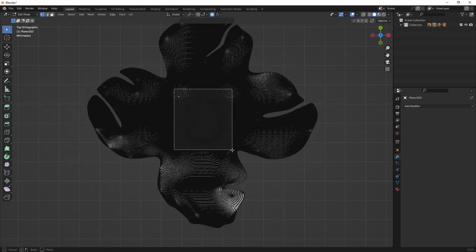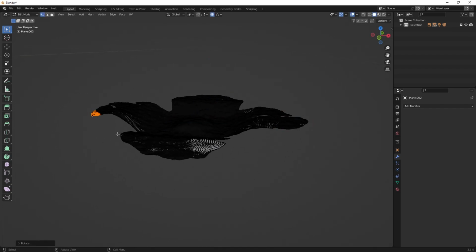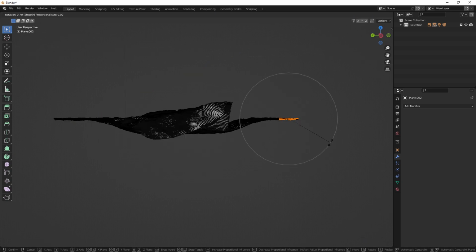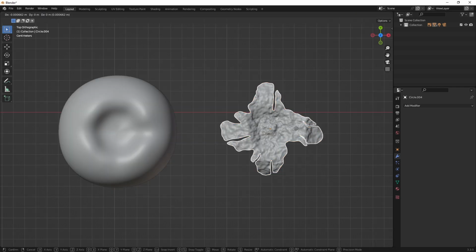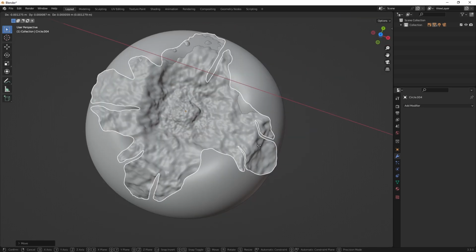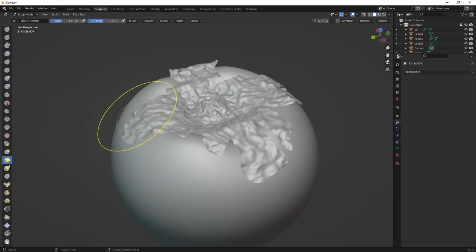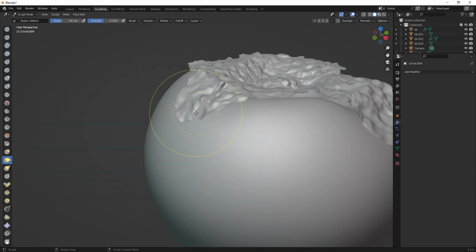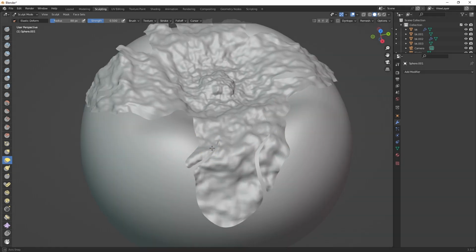The Persimmon's calyx is tightly fitted over the Persimmon body, so we need to rotate the 4 tips downwards. I did this by selecting groups of vertices in Edit mode with X-ray mode on and rotated them. Move the calyx on top, making sure each of the 4 tips fold over the depressions we made in the Persimmon body previously. In Sculpt mode, with the Grab tool, I further deformed the calyx to make the top follow the contours of the body as much as possible. Be careful, you don't want any part of the body poking through the calyx.